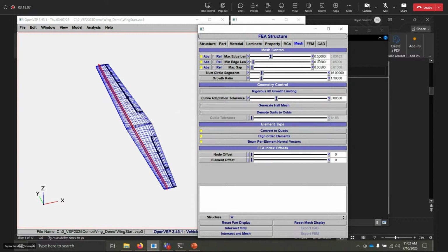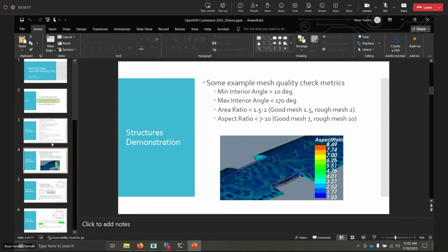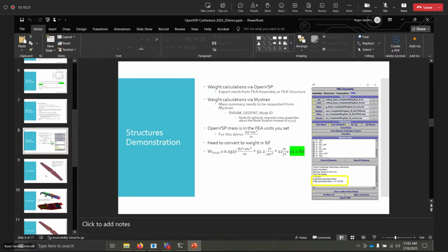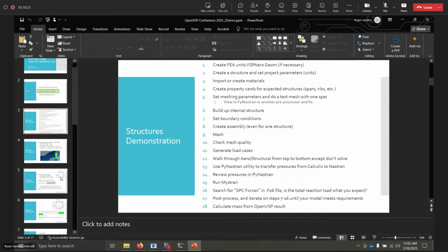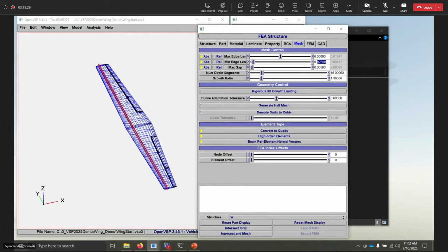So we need this mesh to be representative of inches. So we'll start with a max of like 6 inches. And then I think I put in here what I used. Thought I did. I didn't. So we'll set the smallest one to be a 0.5 inch. We'll back up the max gap.